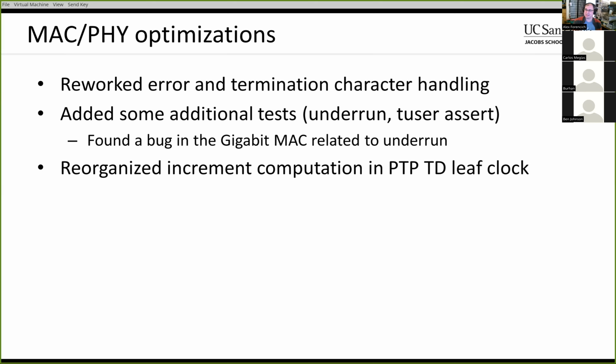So that's one thing I've been trying to do: go through, and if there are some clear places where, okay, I should probably put some flip-flops here, that's what I've been doing. I think it's not going to make a big difference to maybe the slice utilization, but if it's improving the timing performance and potentially helping with routing congestion and whatnot, then I think you're going to get a bigger win versus just, oh hey, we saved a few flip-flops, which I don't think is necessarily all that helpful by itself.